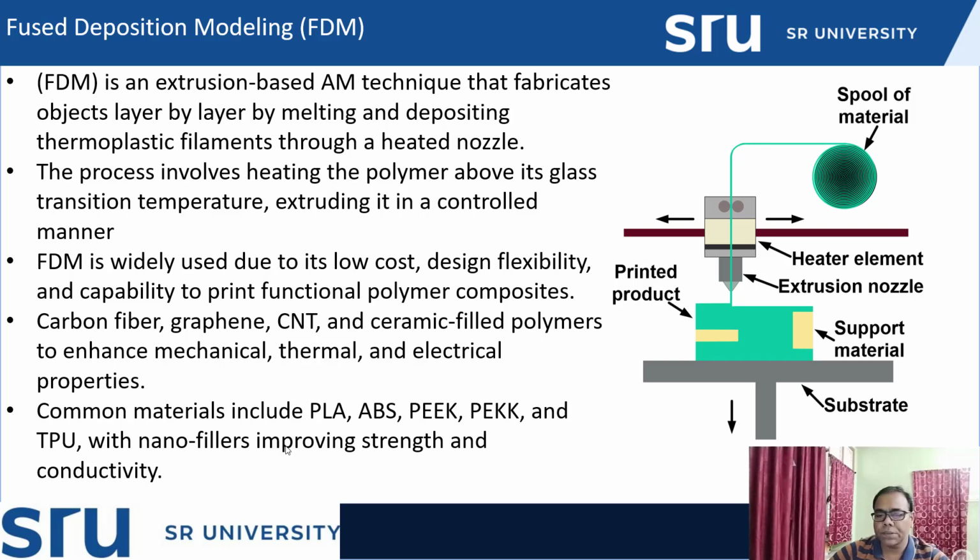So for that purpose, sometimes nanomaterial can also be used as filler, or maybe one can fill with natural fiber, so natural fiber reinforced composite material is also possible using this technique. So these are the details of fused deposition modeling. From that we can manufacture 3D printed composite material also. So coming to our next process.